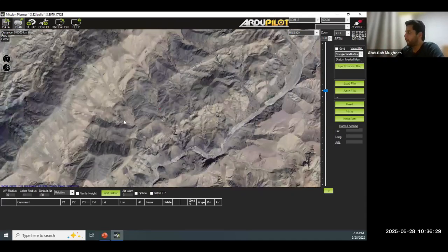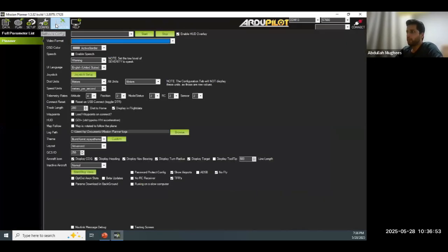You just upload this button, right? Okay, and the drone will autonomously take off. You don't have to give manual commands during the mission. It will autonomously follow the exact path and perform the actions that you described in this tab. Okay, so here you can use this plan tab for the detailed mission.